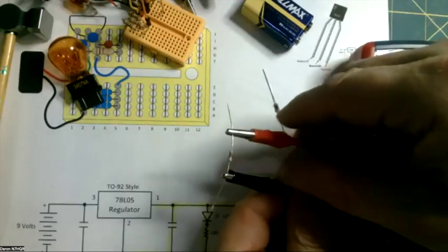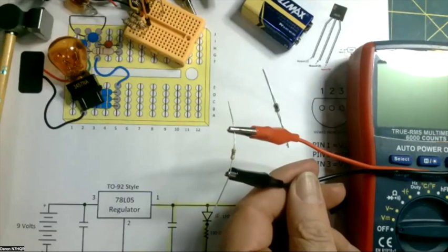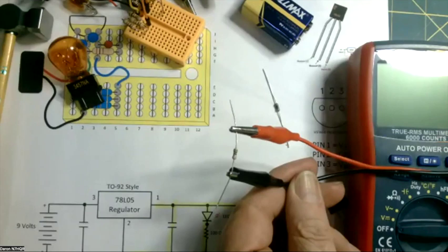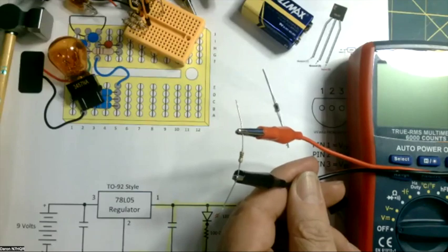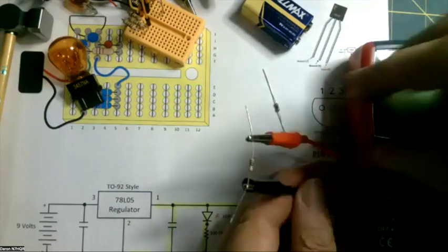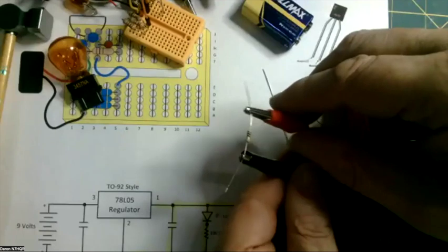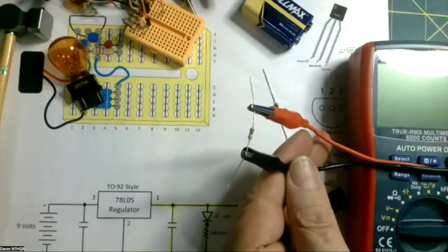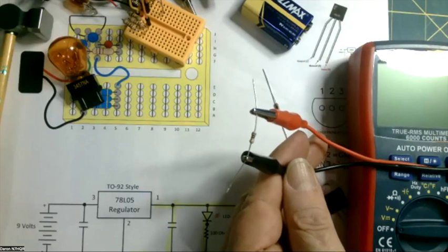Oh, it's starting to warm up there. 3 volts, 300 milliamps. How many watts? 0.97, so almost 1 watt. Is it blackening? Nope, not yet. It's warm. Let's run it up to 6 volts. That's 628 milliamps, 3.7 watts.